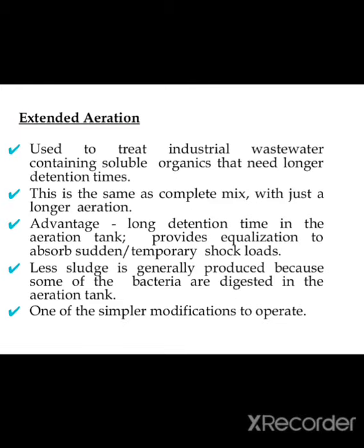Extended aeration. We have seen about the aeration tank. The extended part is that the aeration is done for a long period. It is used to treat industrial wastewater containing soluble organics that need long retention time. This is the same as complete mix, just with longer aeration.